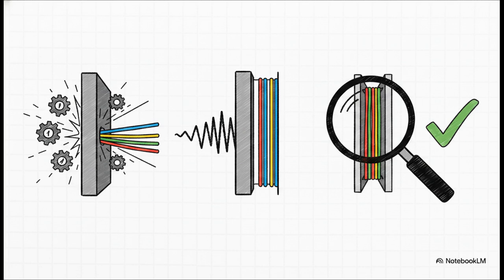Second, by creating defined paths, they limit electromagnetic interference, or EMI, between high-power circuits and sensitive signals. Third, they make troubleshooting infinitely faster, because every single wire follows a predictable route. Plus, let's be honest, a neatly ducted panel screams quality to any inspector who opens that door.